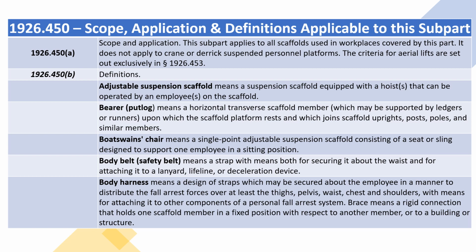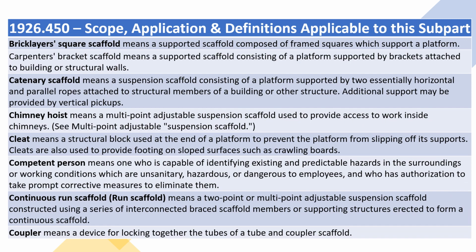Brace means a rigid connection that holds one scaffold member in a fixed position with respect to another member, or to a building or structure. Bricklayer's square scaffold means a supported scaffold composed of framed squares which support a platform. Carpenter's bracket scaffold means a supported scaffold consisting of a platform supported by brackets attached to building or structural walls.